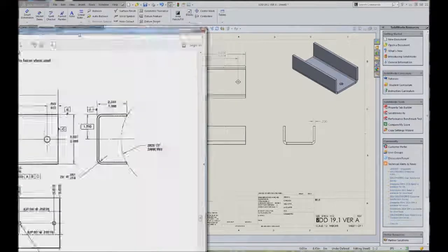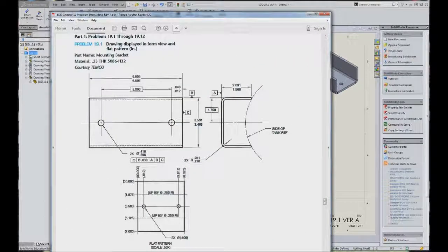You can see on the drawing, like I said, you have datum B, A, C. Make sure they're off the right edges, okay? We will get into GD and T much further down the road, okay? But this is telling me that this is a positional tolerance for the diameters of 30 thousandths. And once we get into GD and T deeper, you'll get a better understanding of what that means. For right now, just emulate this.